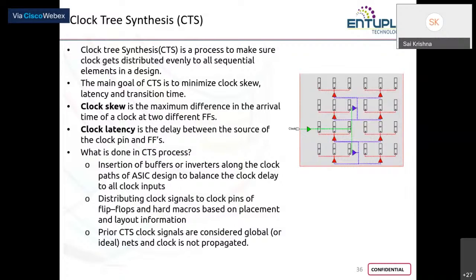I repeat, because of the difference in mobility of holes and electrons, the time between 0 to 1 charging or 1 to 0 discharging at the output is different. That means for a regular inverter and buffer, you have different rise time and different fall time.